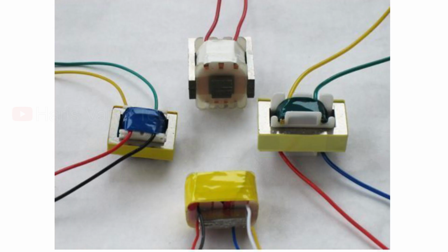Audio frequency transformer or AF transformer. Audio transformers use the isolation property and create isolation between the output speakers or audio circuitry and the transformer's input side amplifier system. In such a case, the primary and secondary winding turns ratio is fixed to 1:1. Due to this, the transformer does not alter the voltage or current level. It only creates isolation between the input amplifier and the output speaker system.